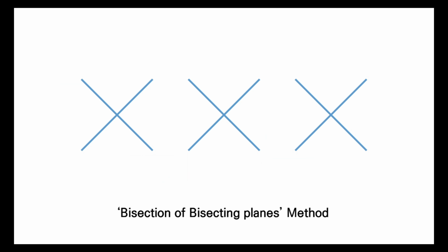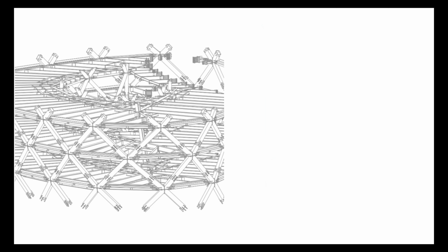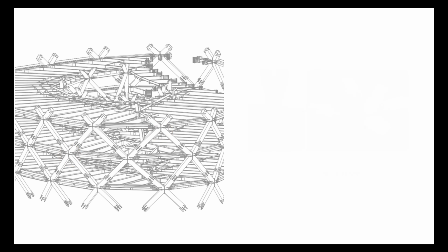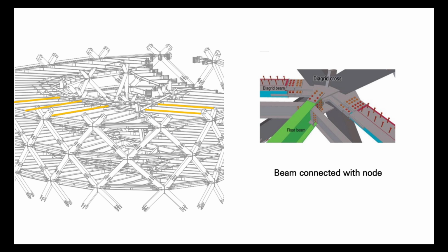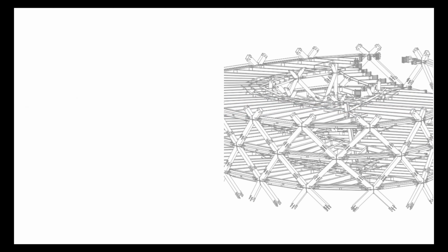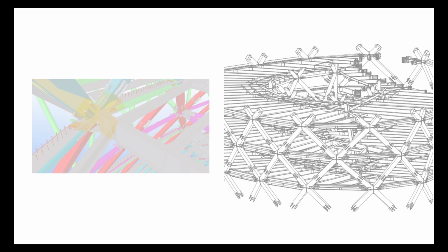These offset values were taken from the Tekla 3D model and used in the design of cruciform nodes. Beams connected to the nodes were moved in the model to avoid member clashing, which could result in eccentric connections. The eccentricity was measured from the model and used in the connection design.